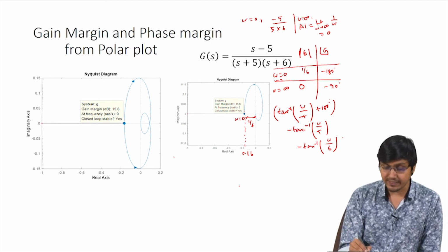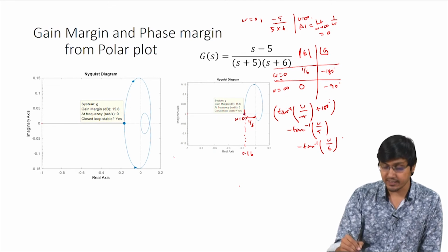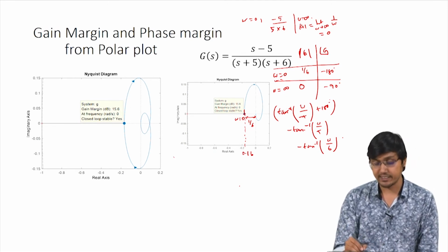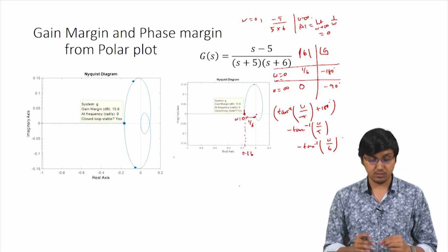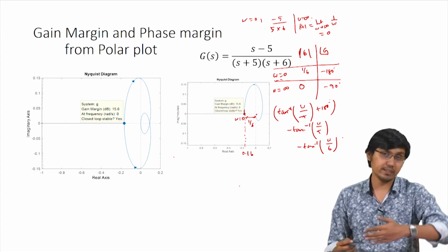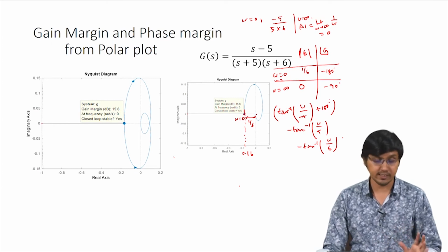You can then find that the amplitude increases at first and then decreases, and it goes to minus 90 degrees at the end point. So this is the polar plot, and if you take the mirror image of the polar plot, you will get the Nyquist plot.